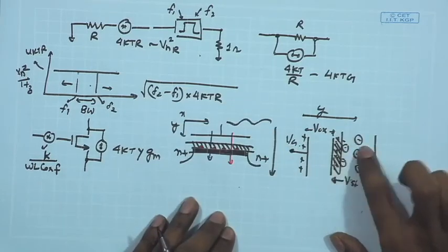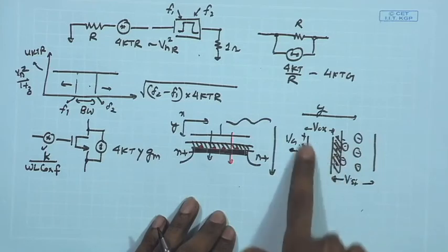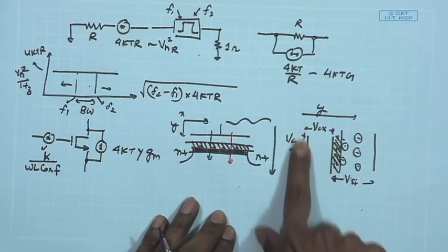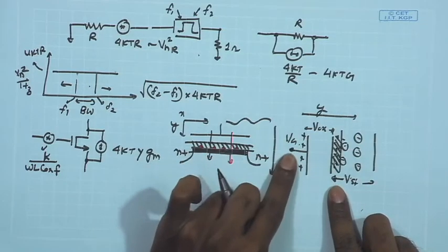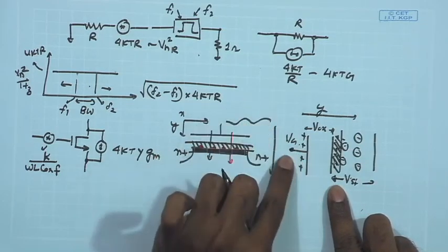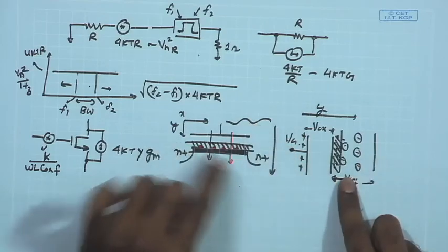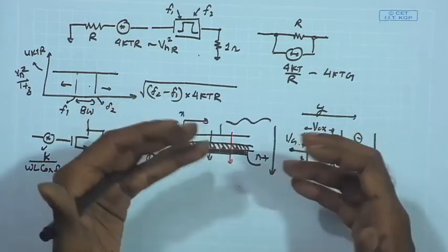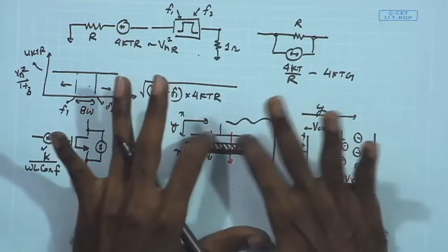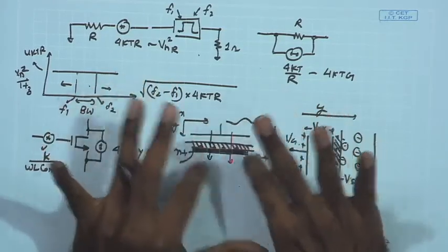So the inversion charge and the depletion charge together combine to balance the total positive charge that you have put on the gate. As a result, when you increase or decrease the gate voltage, the total charge on the gate increases or decreases. That is what we do, right. While understanding the capacitance of circuits, we also discussed how parasitic capacitances arise. Ultimately, it is because of the charge balancing between the gate and the substrate.